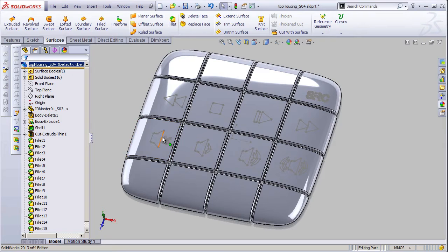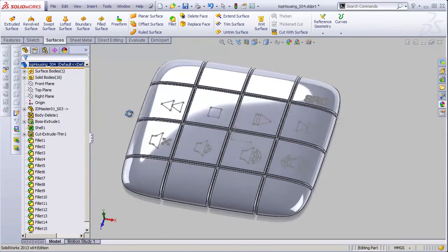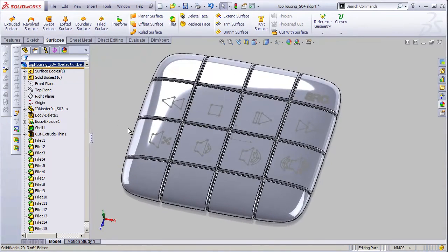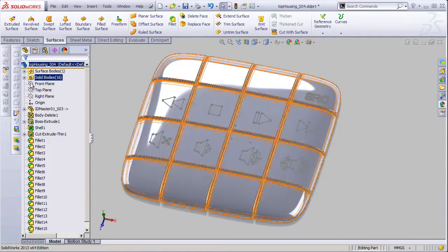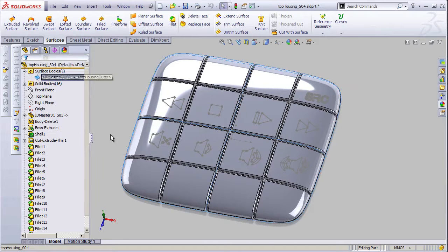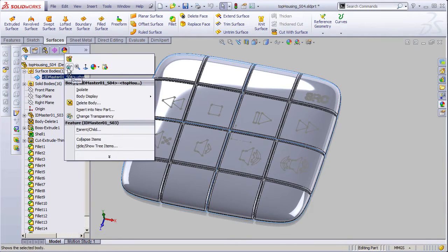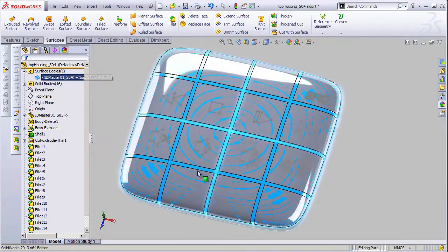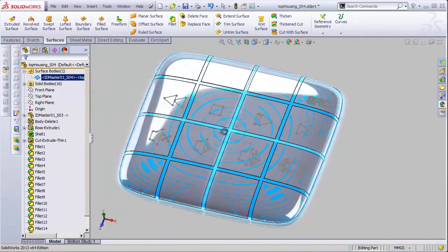If we were to use these to create solids, then those solids might actually end up by accident in some of our manufacturing geometry or 3D printing geometry or something, and that's usually not what we want. So if we make these surfaces, then we don't have to worry about that contingency, and everybody rests a little bit easier. So what we can do is go back to that surface that, remember, we still have this exterior surface geometry here that represents the outside face of this thing.